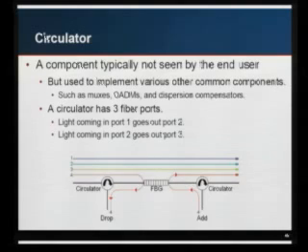So here's an example of how an OADM works. There's one of those Bragg grating filters that cuts off or reflects only a specific frequency of light and passes the other through. The specific frequency of light that you want to drop gets reflected, it comes back in port 2, and then you drop it out port 3. The frequencies of light that you don't want to filter just go straight through port 2 and pass onto the other side. So that's really how all these systems tie together, with the circulator. It also keeps light going one way.